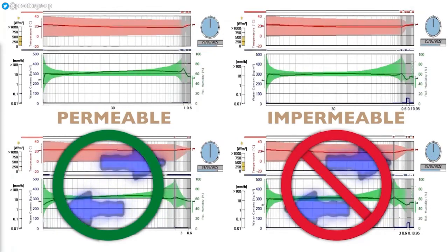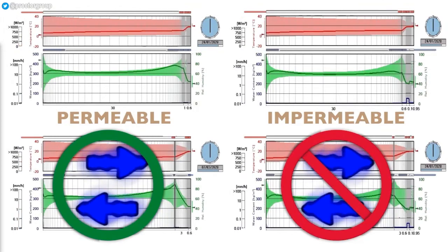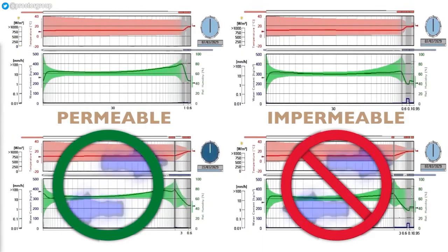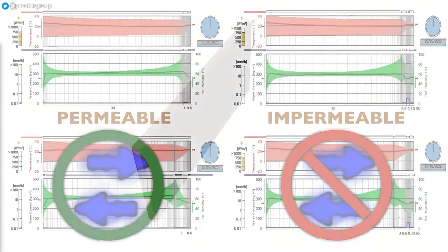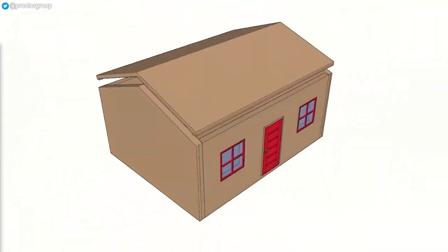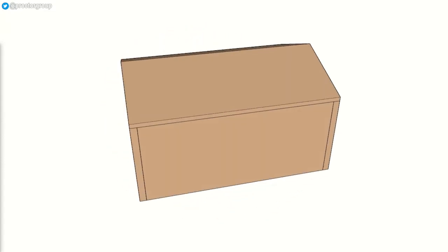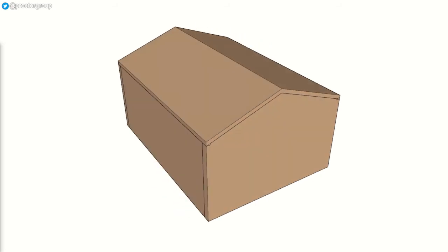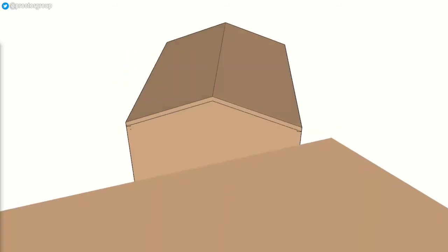So, considering all of the above, the risk of condensation, counterintuitively, is lowest when we omit the vapour control measures and limit the insulation thickness. The additional detail presented in this more complex assessment also allows the designer to better quantify and hence manage the specific risks associated with this insulation upgrade.